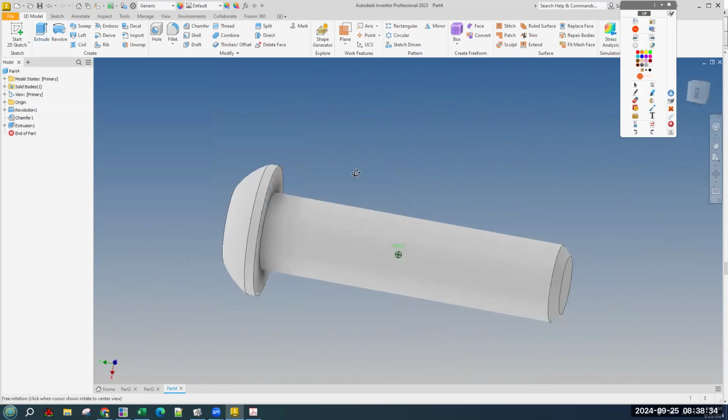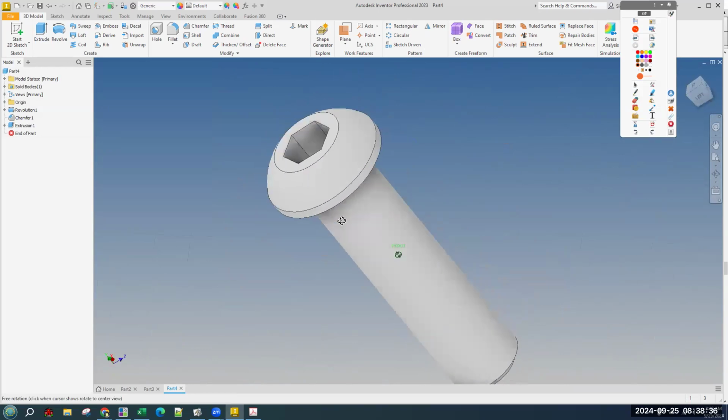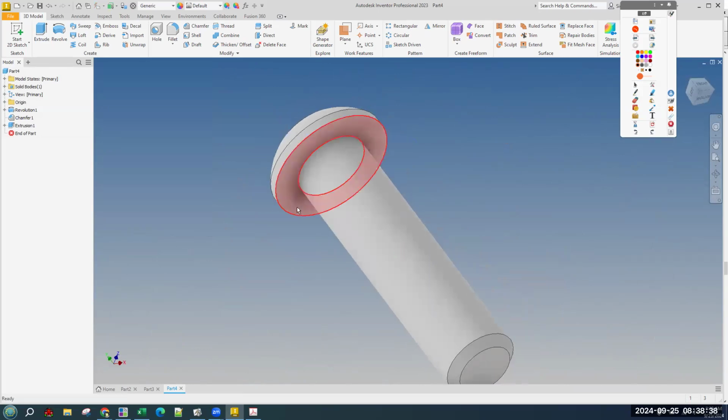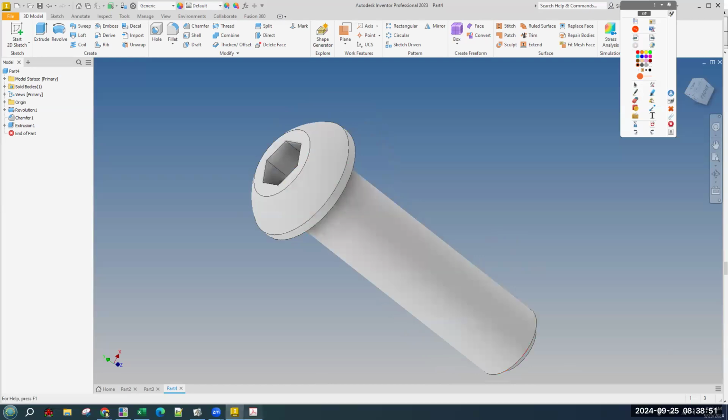Okay, and so there is most of it. The only other part feature, it's cut extrude. You have to switch it to cut extrude, and the depth is 0.111. Okay, the only other part feature for this one, and it'll be the last of the day, are these threads.